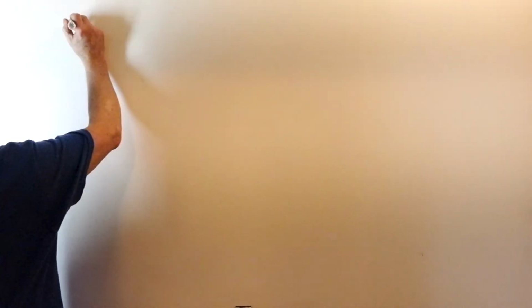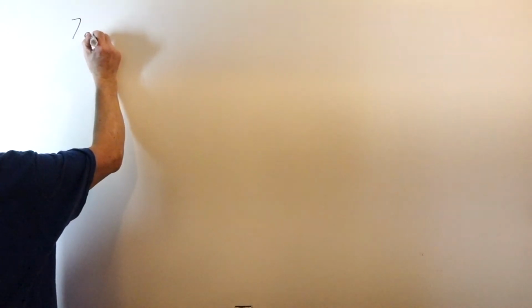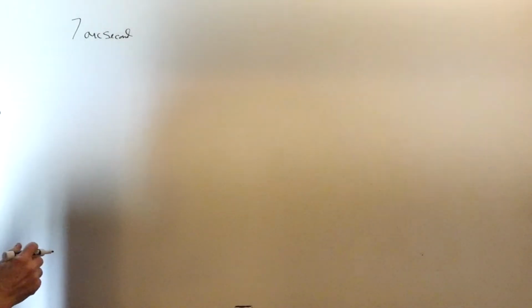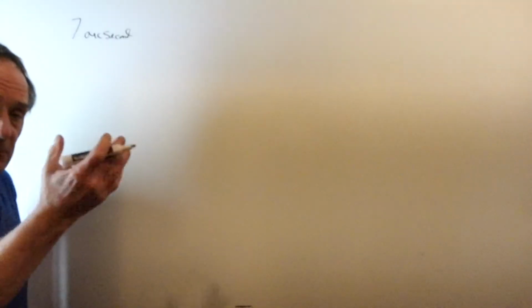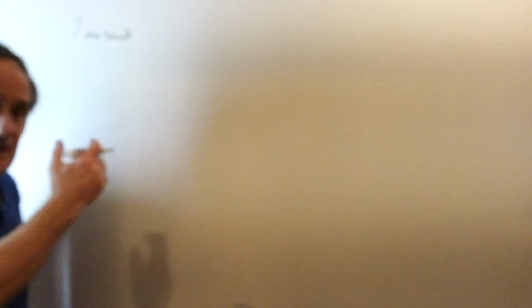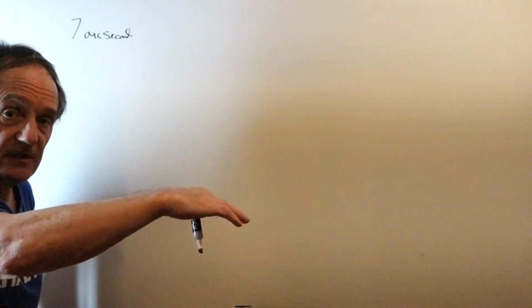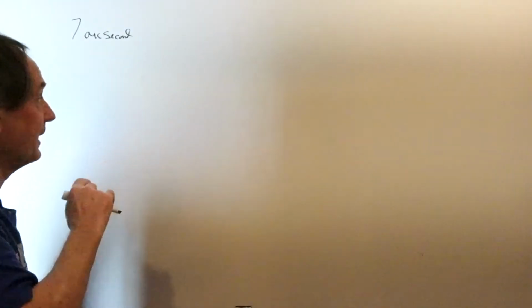I have calibrated my Topcon auto level several times and determined its uncertainty to be within 7 arc seconds. Let's look at what that means. 7 seconds of an arc, or 7 arc seconds of angular error. Let's see what that translates out to, say, out at a mile, what the uncertainty in measuring a height might be.